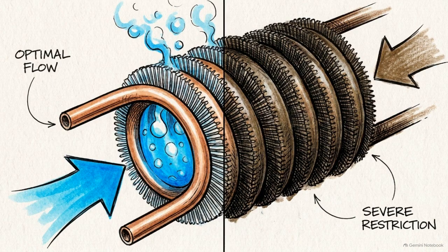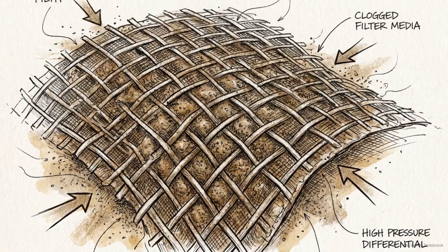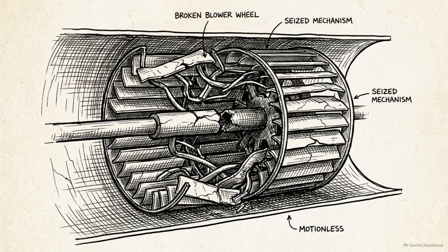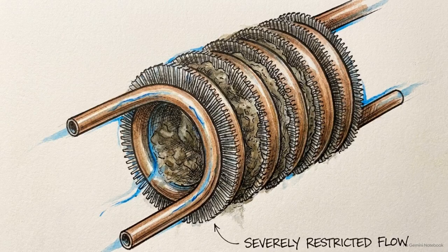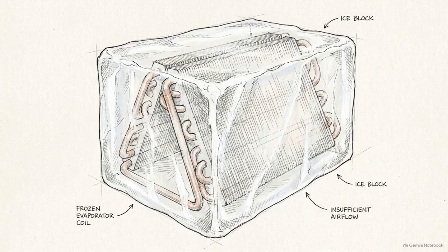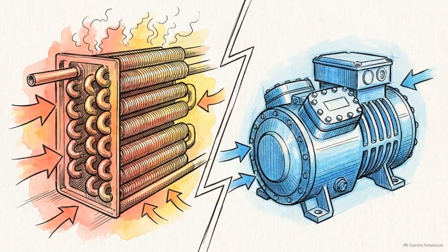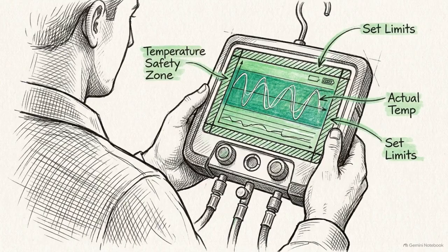External factors immediately disrupt this delicate thermodynamic balance. A dirty air filter or low blower airflow lowers the overall heat transfer rate. This forces the evaporating temperature to drop below freezing, ultimately causing moisture in the air to freeze and form thick ice across the coil. Operating an evaporator is an eternal compromise. The system must push the coil to absorb maximum heat capacity while rigorously maintaining a strict thermal buffer to ensure